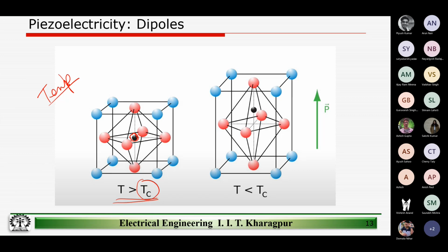Typically, the way we design the transducers, even without application of the force, there is an existing polarization already there, meaning there will be an existing dipole moment in the material, even without the application of the force. On the application of the force, the dipole moments inside the material change, because of which the net charge on both plates of the transducer changes.